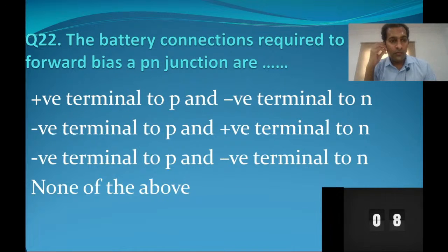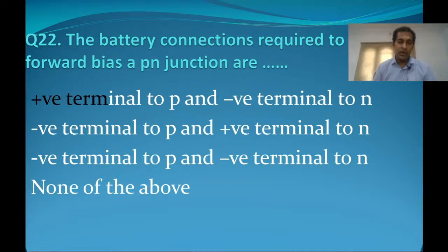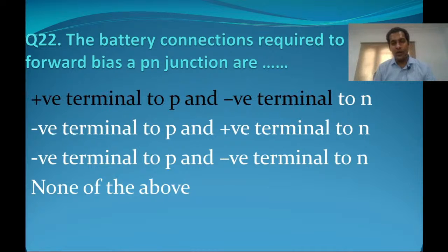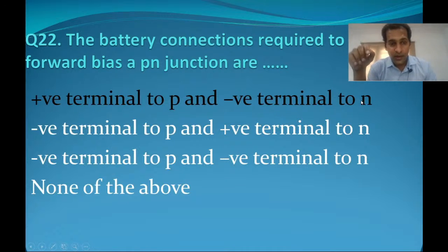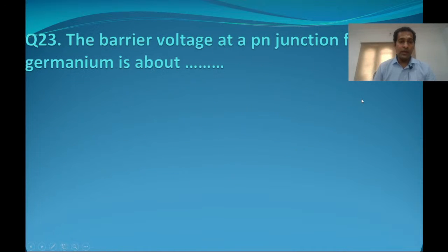Forward bias means on. We should connect the P type to positive, and negative to the N type. How shall we connect it? Your time ends now. The answer is positive connected to P type and negative connected to N type. You can remember it like P to P and N to N for making it forward bias. So what should happen for making it reverse bias?